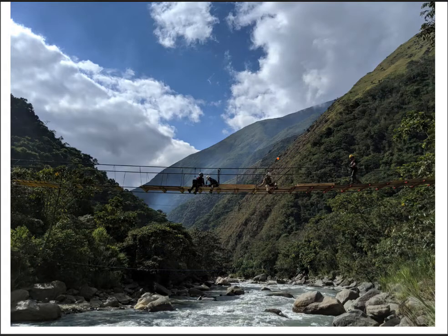So what you really need to do is, let's go gray here, cut into the mountain here, and we'd put our abutment here, but then you have all of this on top, and you can't just have a huge vertical like this, so maybe you're going to have to bench it like this, and it just ends up being a massive amount of earth that you need to move. So this is why that is not feasible.